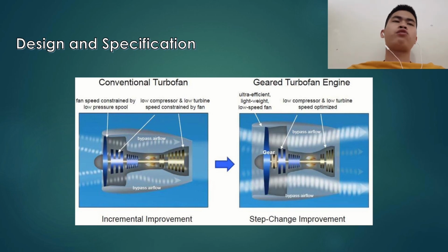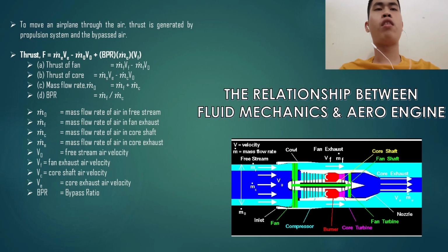At high bypass ratios, the tip speed of the low pressure turbine and compressor must be relatively low, which means extra compressor and turbine stages are required to keep the average stage loadings, and therefore overall component efficiencies, at an acceptable level.